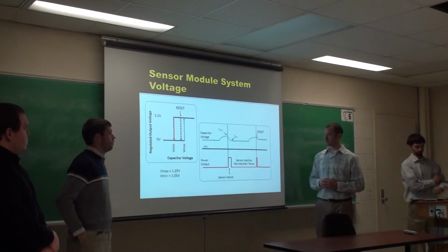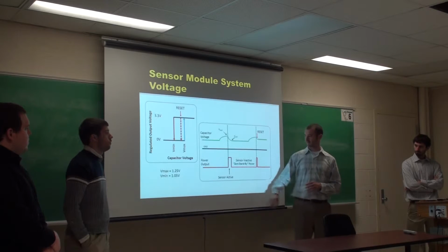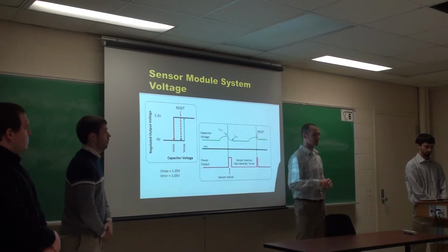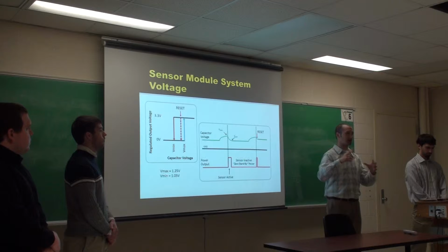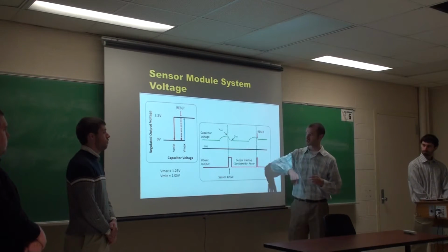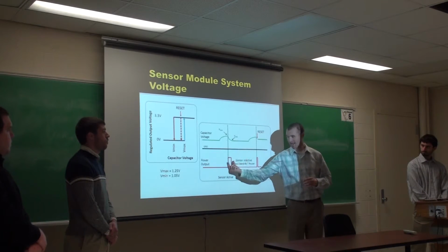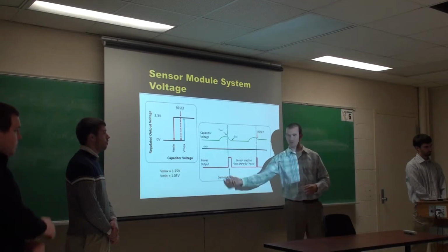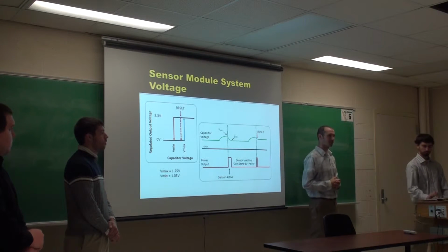So this is kind of the idea of how the voltage from the capacitor charges and discharges, and how the power of the sensor goes. As you can see, it's a flat line of capacitor voltage, and then when it gets more RF energy, depending on how far away it is or the frequency it's capturing, the efficiency, we see once this capacitor charges up to its Vmax, this discharging time right here is the time it has to do all of its processing, all of the sensor and everything. So we're talking milliseconds. This is a very, very quick time span.